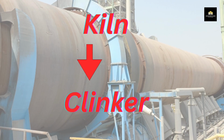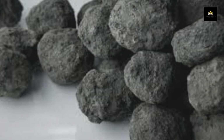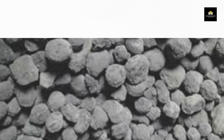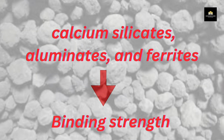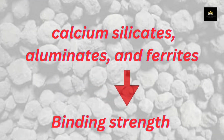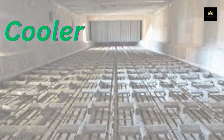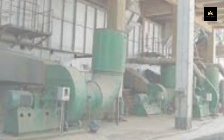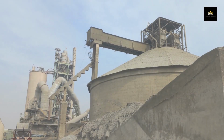Inside the kiln, complex chemical reactions take place, forming small marble-sized nodules known as clinker. These clinkers consist mainly of calcium silicates, aluminates, and ferrites, all essential compounds that give cement its binding strength. Once formed, the clinker is cooled rapidly in a clinker cooler using air. Cooling is critical to preserve the quality of the cement and prevent unwanted crystal formations.